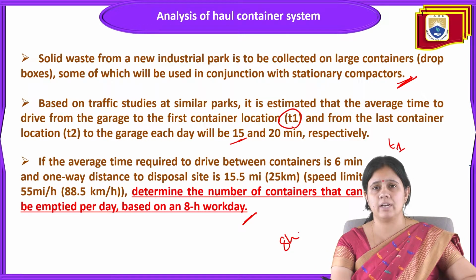So we have to calculate using the average time required to drive between containers of 6 minutes, a one-way distance to the disposal site of 25 kilometers, and a speed of 88.5 kilometers per hour. So determine the number of containers that can be emptied per day based on an 8-hour work day.